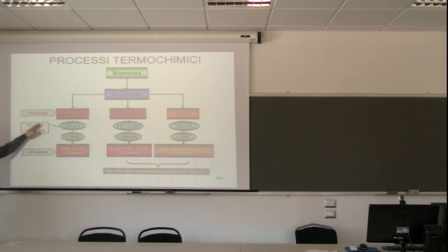So you can see an important parameter, which is the equivalence ratio, the ratio between the oxygen you give to the thermochemical process and the stoichiometric oxygen you need for the complete combustion. Okay, what does it mean?